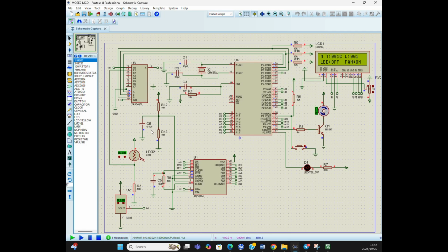The system works correctly. The sensors respond accurately, the fan and LED react in real time, the LCD displays all the information clearly, and the mode switching works perfectly. One challenge I faced was controlling 2 analog sensors with one ADC, but I solved it by using a 74HC4051 multiplexer. I also had to carefully adjust the transistor circuits to make sure the LED was not always on.